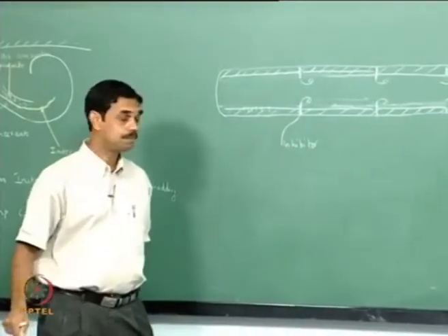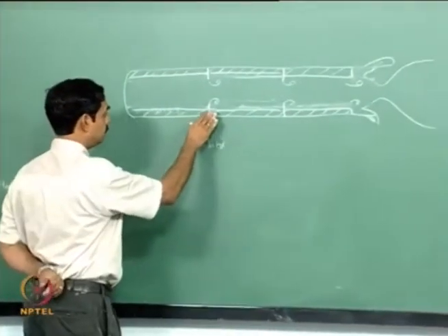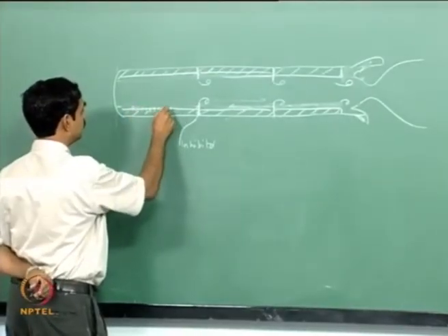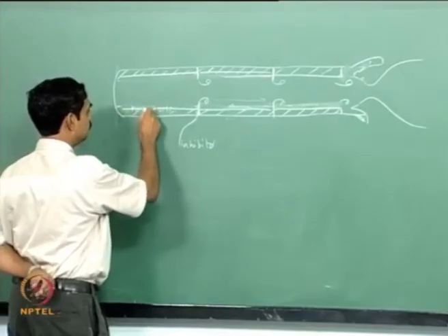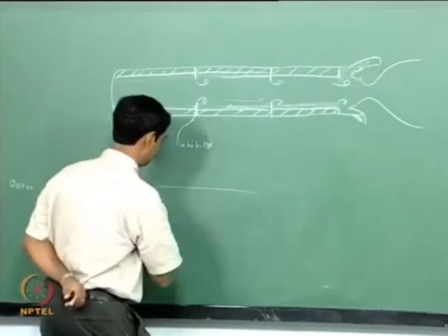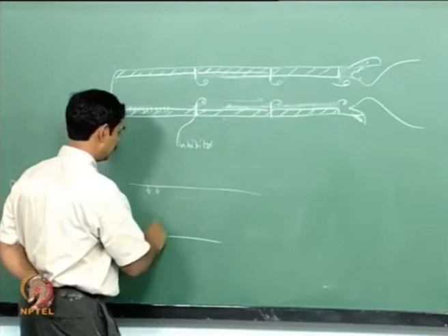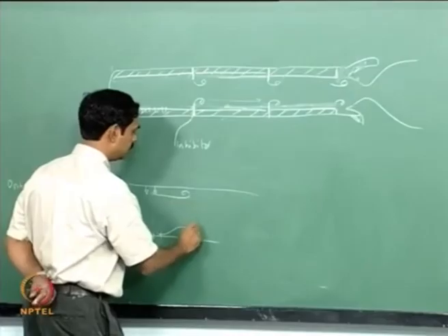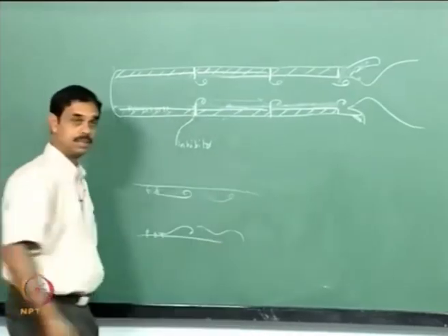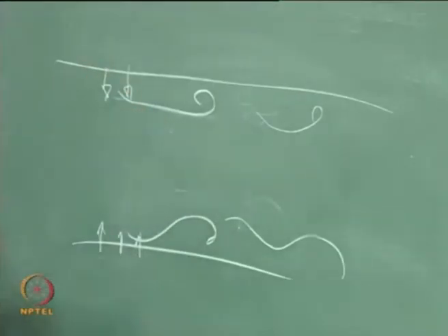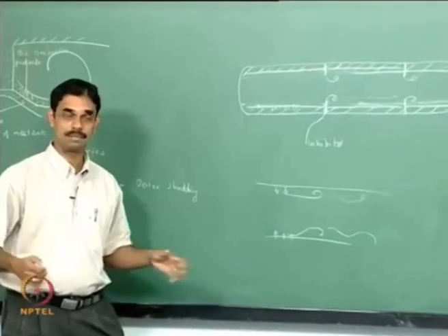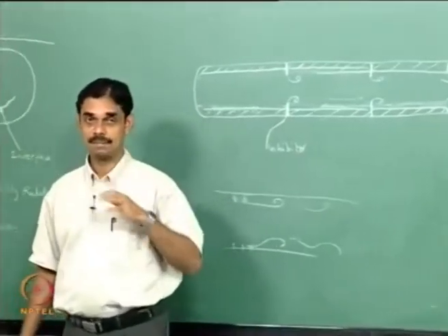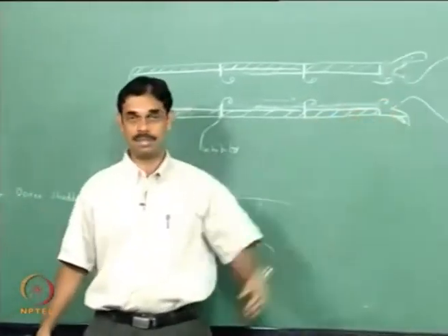Now even if you don't have these inhibitors, if you have radial injection, and propellant burning is like a radial injection, so if you have a situation where you have gases coming out this way, eventually there will be vortices being set up, because this flow, the radial injection flow, is inherently unstable. And even if you do not have vortices, and if you have a gimbal nozzle and there is a cavity there, there is a possibility of making sound.